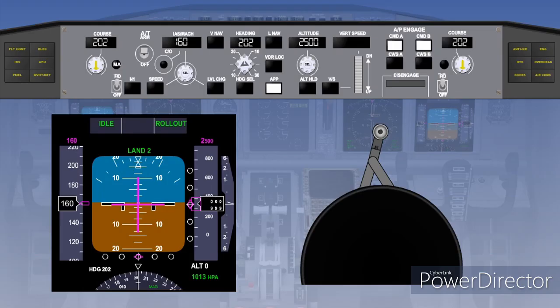This will allow the aircraft to maintain the centerline of the runway, even after the airspeed has fallen below the speed at which the rudder is effective. Some aircraft may use a runway guidance system, giving the pilot commands to move the rudder left or right to maintain the centerline. With rollout control, the autopilot will remain engaged until the pilot disengages it at some point during the rollout.